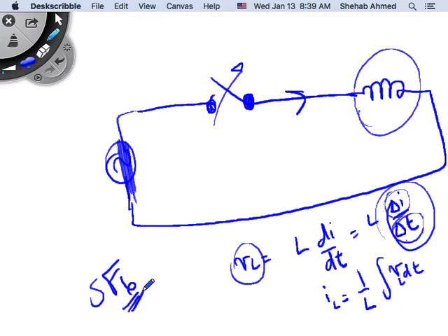So if you bring 50 kilovolt breakers from different technologies, the gas insulated breaker, the GIS breaker, will be the smallest. Why? Because it can quench the arc better. That's the only difference between them, the arc quenching mechanism. If it can quench the arc quicker, I can make it smaller. But it's more expensive. So you use it, for example, if you go to work for RasGas or Qatar Gas or whatever, and you go to the LNG trains that they have.